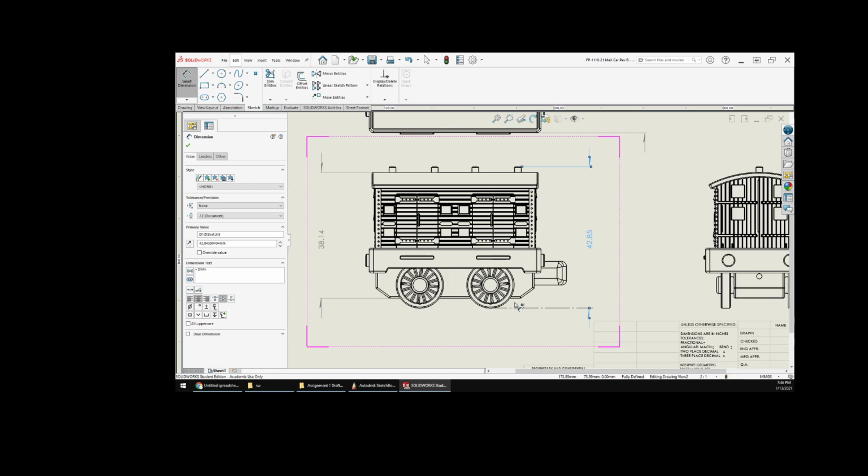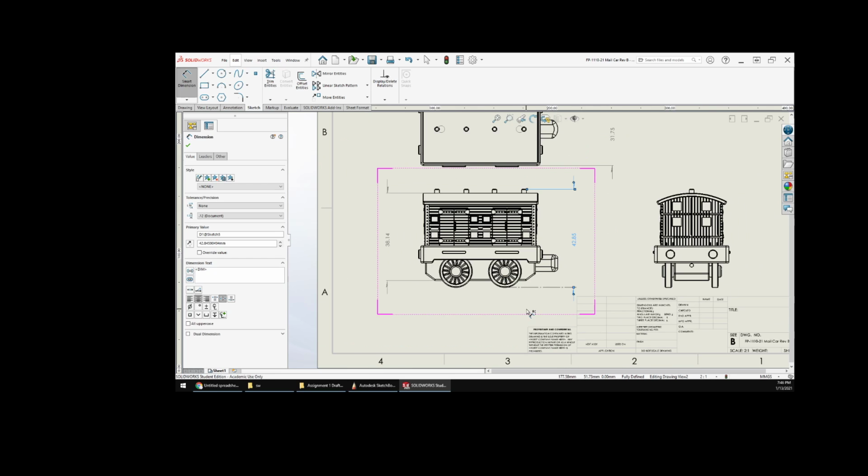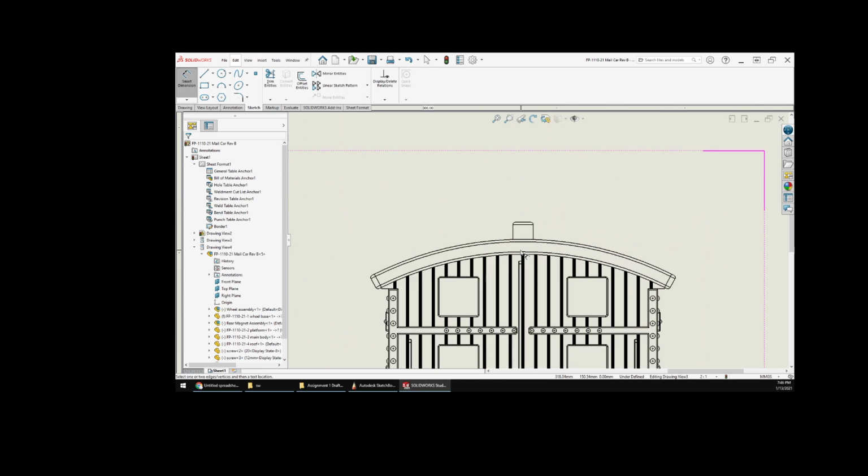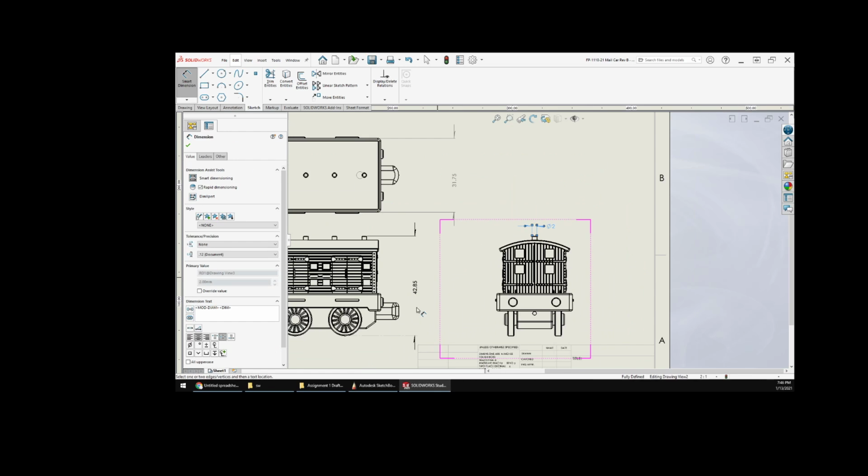And you can see I did what I told you guys not to do. I've got some very unique numbers on here. But that's okay. Now, you can kind of see here, I got rid of my default. I changed it. This might be fine if I'm doing a tight dimension somewhere where I don't want those big leader lines coming in. So that works there like that.